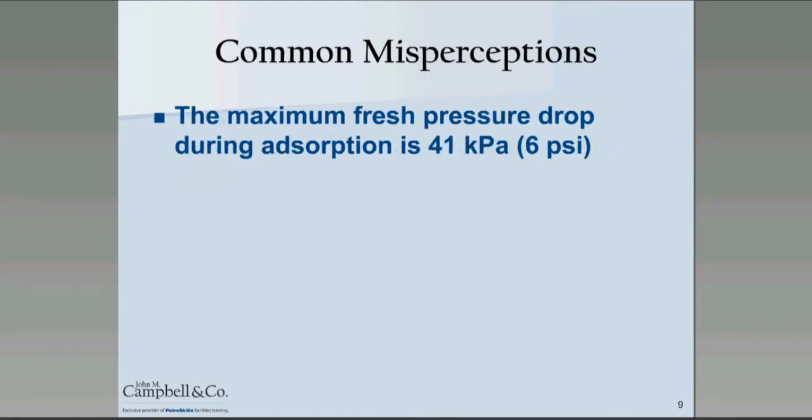The second misperception is that the maximum fresh pressure drop a bed of molecular sieve can handle is limited to 41 kPa or 6 psi. Molecular sieves can handle much higher pressure drops, probably more than a mesh and grating bed support system can withstand.